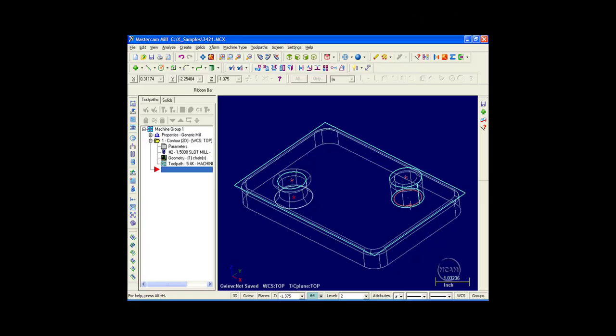The red circle right in over here is used in the toolpath that comes with this file. And this is a contour with a slot mill that's going to come right around this standoff and cut a thread relief before we cut our threads on it. We're going to take a look at creating both an internal Threadmill toolpath and an external Threadmill toolpath.